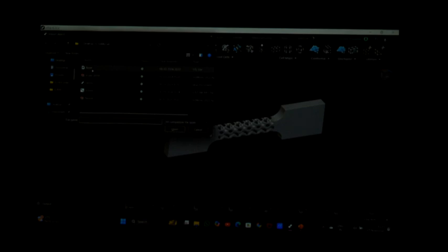One example I will tell. Which one should I take, brake pedal or bone? No, brake pedal is again a CAD body only. Bone means an STL body. CAD body we have already explored, the same thing. So I can take the bone. Bone means, in between I am applying a lattice, but there are no faces there to select. Here we can easily select the faces, right? So I can take this.